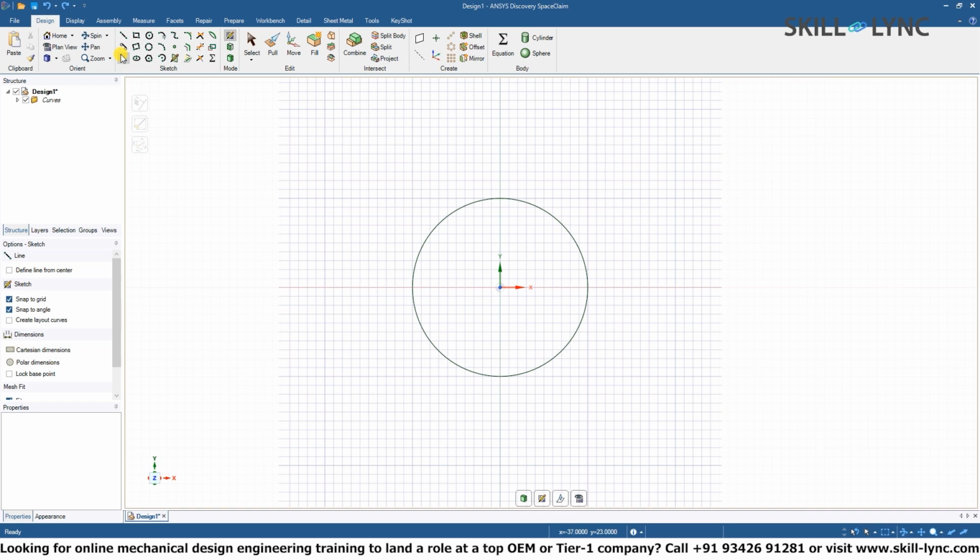It does not have a physical entity or a body. It's just something you can select as reference geometry. So you cannot pull 3D geometry off of a 2D line, but you can define the construction line as an axis or a specific point for other processes.